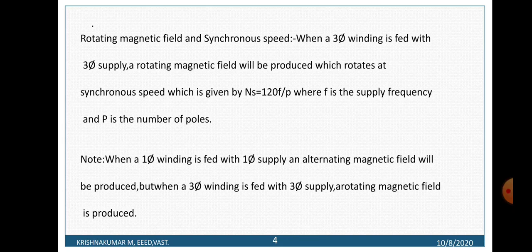When we give three-phase supply to the stator winding of a three-phase induction motor, a rotating magnetic field is developed in the stator, which is rotating at synchronous speed. Ns is equal to 120 F by P, where F is the frequency and P is the number of poles.